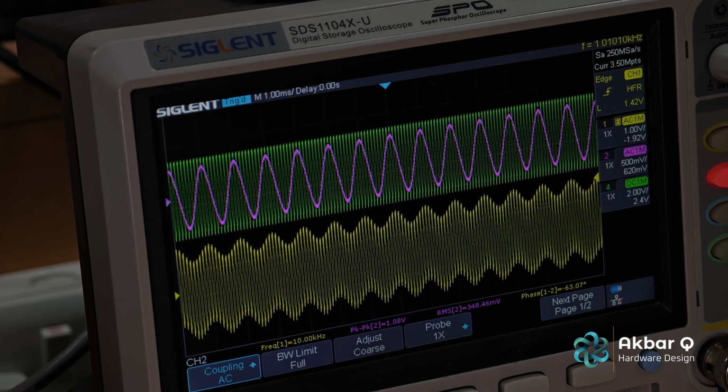In amplitude modulation, we take a high frequency signal called the carrier and we vary its amplitude according to a lower frequency signal, which contains the information. This could be audio, for example. The key idea is that the frequency of the carrier stays the same, but the amplitude changes in proportion to the message signal, where the carrier frequency is much higher than the message frequency.